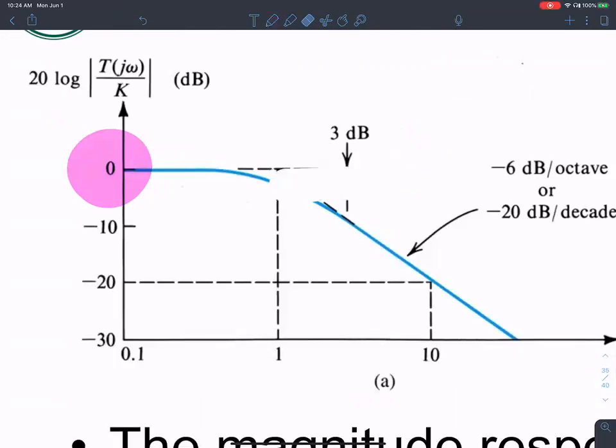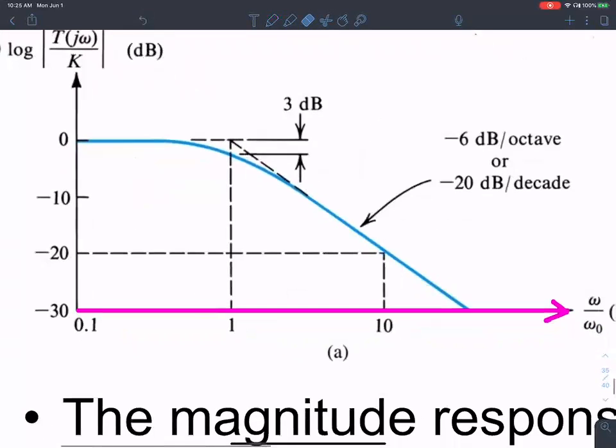That's the behavior of the magnitude of gain with respect to frequency. As the frequency increases, for a single pole behavior, for a pole at that frequency, it begins to fall at 20 dB per decade. Okay, questions, please. I have a question. Yes.